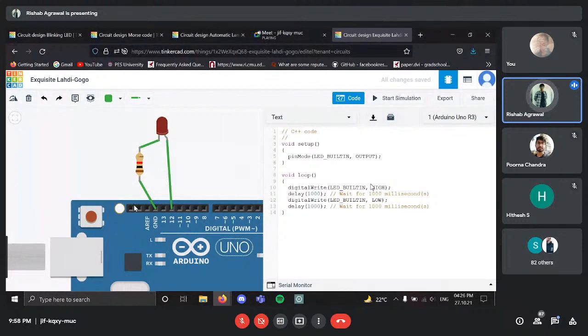And generally, this is a misconception I have heard of: the reset button here on the Arduino board doesn't really factory reset your Arduino with the code that's inside, like the Arduino losing its memory. It's more like running the void setup again.